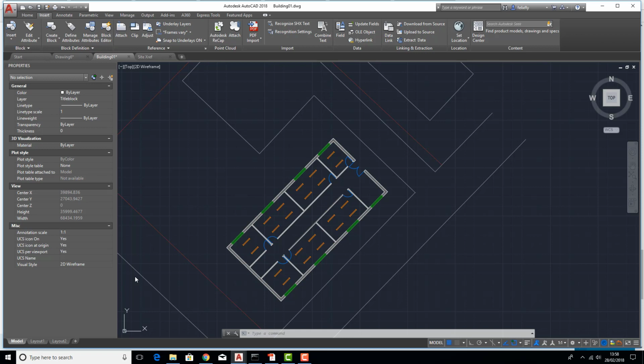A lot of it's driven in this day and age by email. We tend to email drawings around rather than printing them out and sending them, so you just need to email a particular model. Generally people will have the site layout, so everyone working on the project will have the site layout and the architect's layout, and only get sent the things they need that may have changed. It's just a case of bringing in a new Xref, replacing the old Xref.